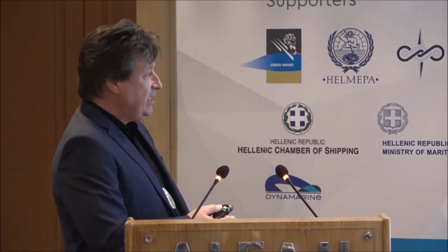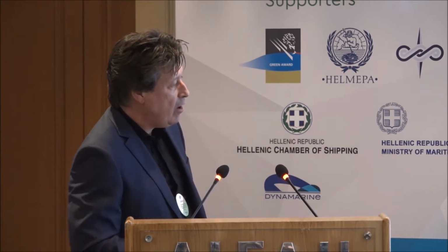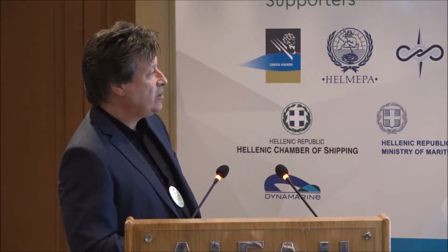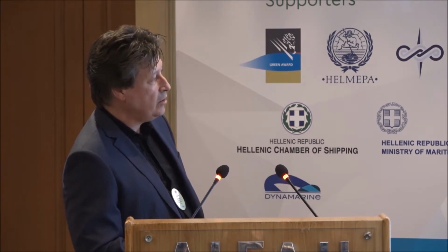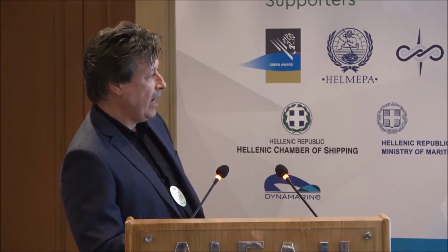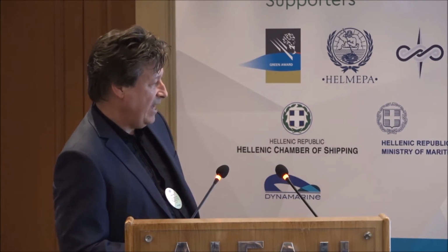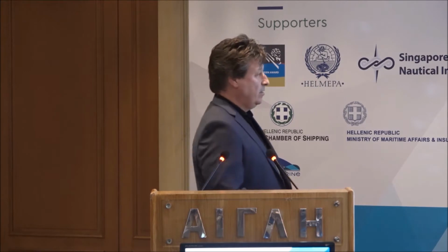Dynamic analysis, so I mentioned that's time variable. All the x-axes here are time. This is 3 hours. This is the variability of the wind speed and direction, current, surge, yaw, and sway, X and Y forces, ship to shore fender curves, ship to ship fender curves. So you can see it's all varying with time, and line loads.